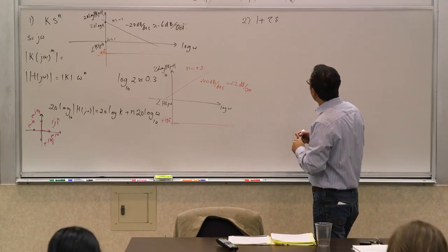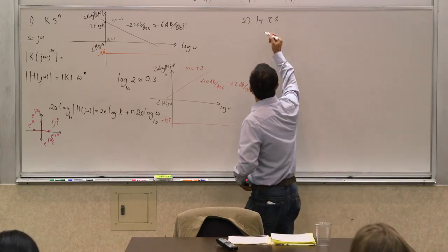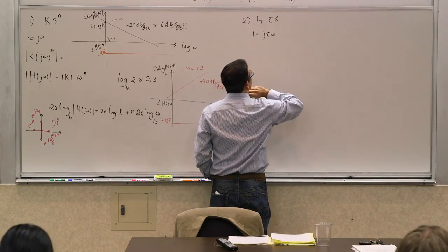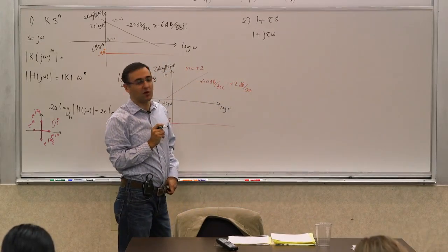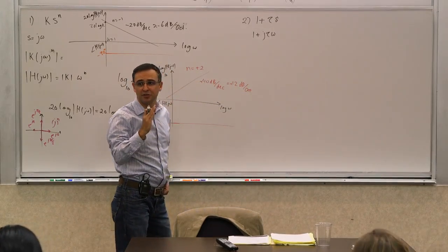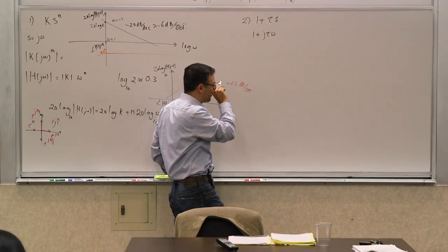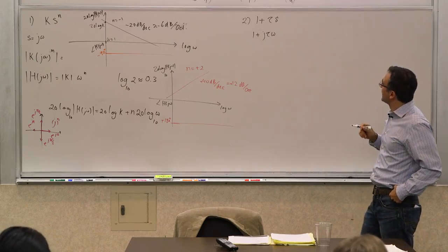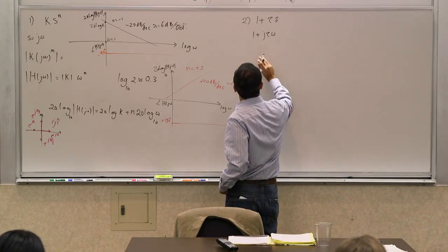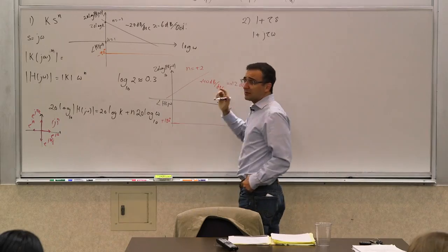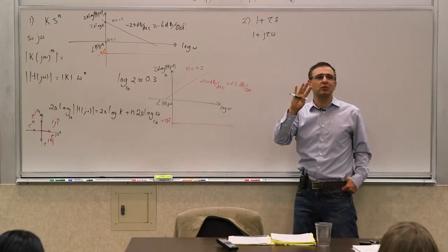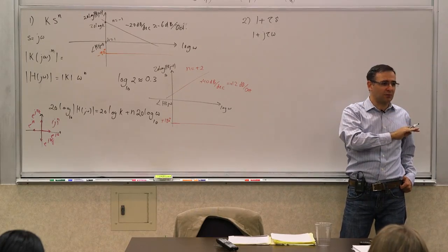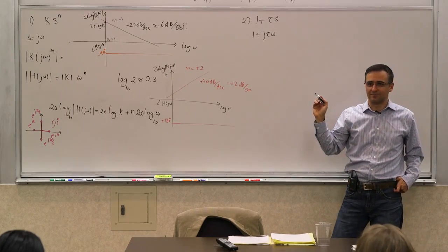So how does this look? First of all, we are really not looking at that. We're looking at this if you're talking about a Bode plot, with s being j omega, because it's a very special kind of perturbation. It's not any generalized frequency. It's really specific. It's like sines and cosines, really. Now we can ask how this looks on a Bode plot. But let's look at two special cases. This is what you do with Bode plots: you generate asymptotes. And once you know all the asymptotes, you can generate the plot very easily.